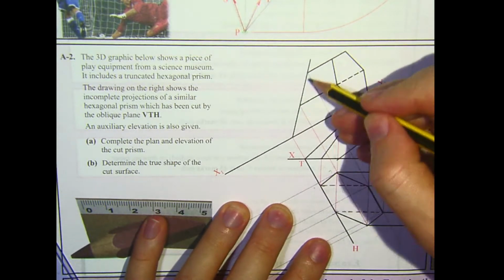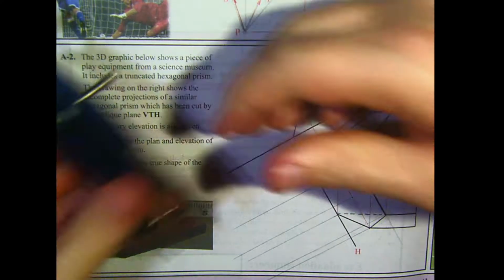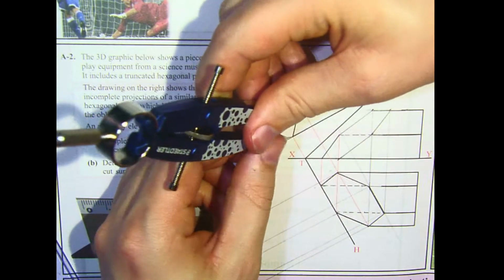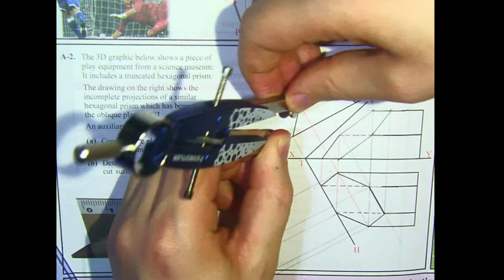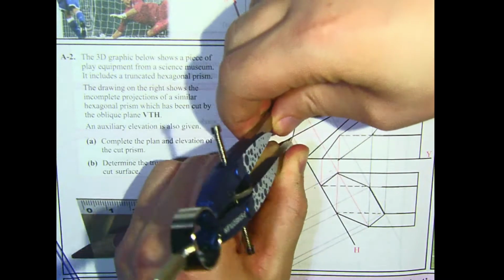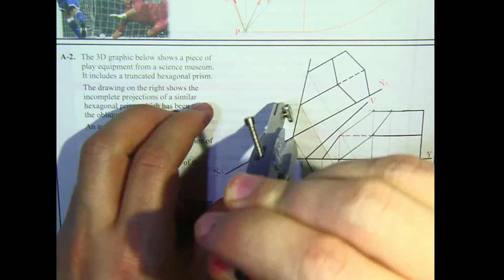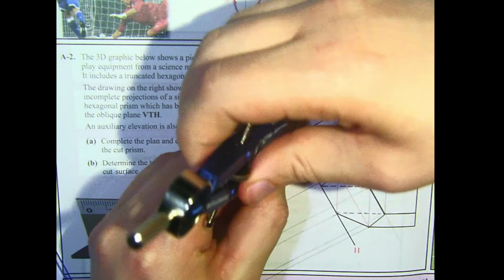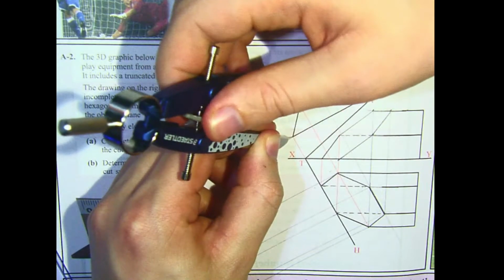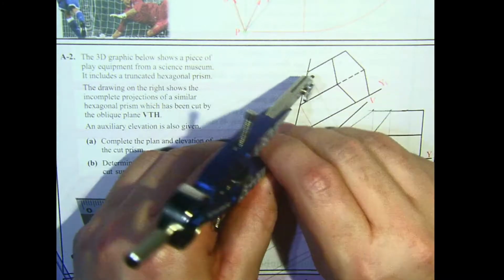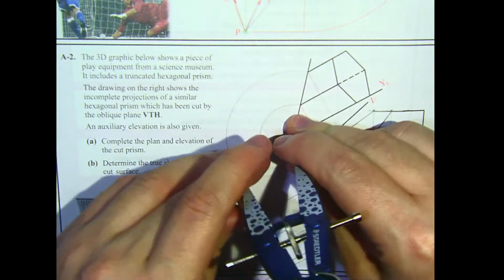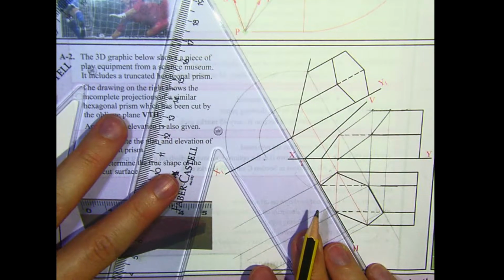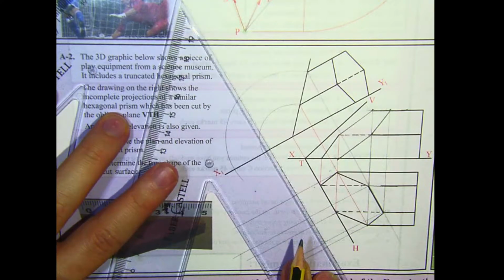And we already have all of these points up here, so what we're going to do now is rotate them around this point here on the x1, y1 line. So these distances, rotating these around until they're flat, so that'll be on the x1, y1 line. These points here, and project them now back down parallel to HT.